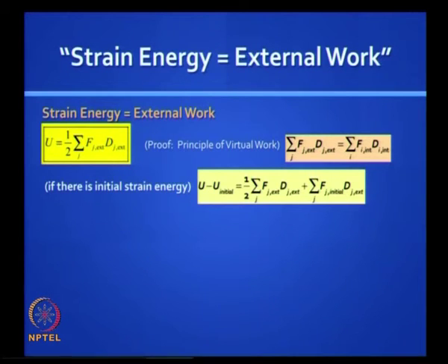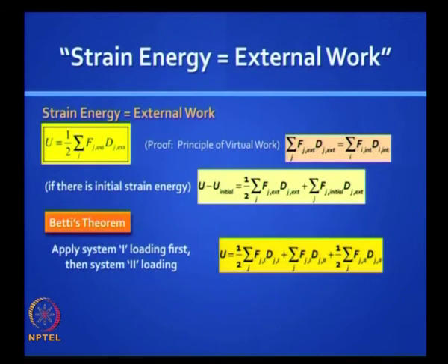But if there is some initial strain energy locked into a system, and often you have that, for example when you load rolled steel beams you have some residual stress locked into the beam, then actually you need to subtract that part, because it is only the incremental change in energy that you are measuring and you are calculating.